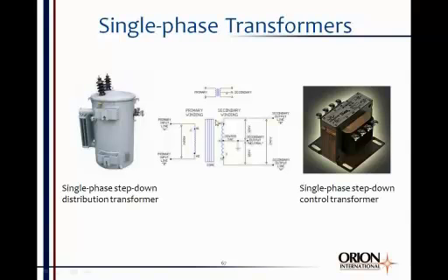On the secondary side, this is a single-phase transformer. It has two phases, and then there's a center-tapped neutral, which is grounded, establishing the neutral. That's called the grounded conductor. So this is what they run into your house. You'll have 120 volts reference to ground, or the center tap, on both phases, and 240 volts phase to phase. So that's a single-phase transformer.